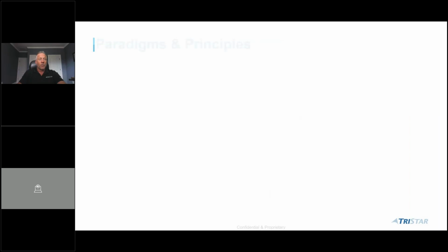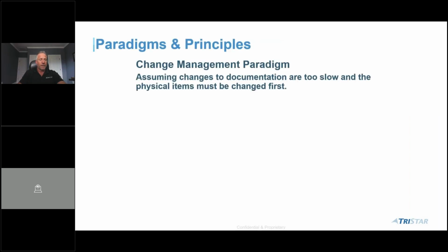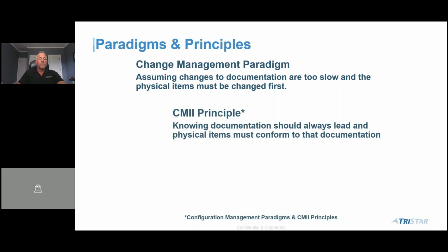Okay. And so when you look at the first paradigm, and this happens a lot when we get into these discussions, companies and employees assume that changes to documentation are too slow and that the physical items must change first. Okay. We see that all the time. And the CM2 principle is knowing documentation should always lead the physical items. And the physical items must conform to that documentation.